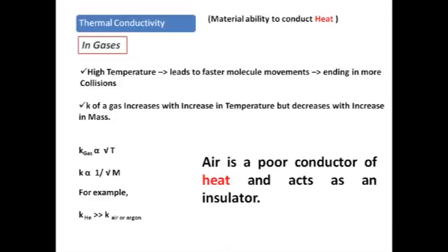To prevent formation of water droplets or dew formation on the window surface, 2 layers of windows with glass are used with air in between them, so the rate of heat transfer is minimized. Many cold storage walls are constructed in 2 layers with an air gap so that the rate of heat transfer is minimized. So air, being a poor conductor, acts as an insulator and hence reduces the heat transfer.